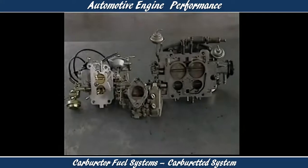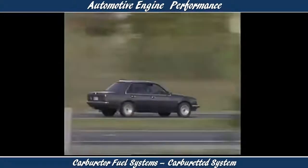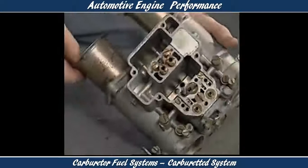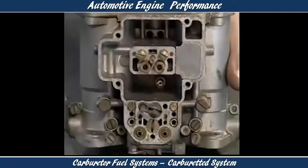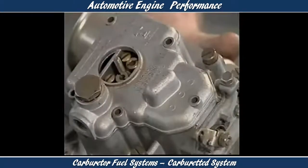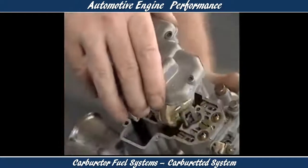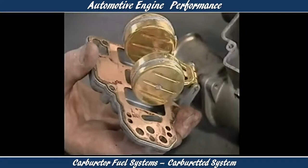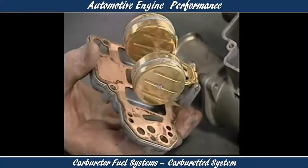Carburetors can have a single barrel or 2 or 4 barrels. Extra barrels improve performance, particularly at high speeds, letting more air enter the cylinders than with a single barrel. Two barrel carburetors have two outlets to the inlet manifold and have two basic designs. One has a common float chamber, but each barrel has a complete set of all other circuits, and the throttles can open simultaneously. The float chamber may be straddled by two connected floats that almost surround the air passage. This leaves it unaffected by cornering, climbing, accelerating, or braking.